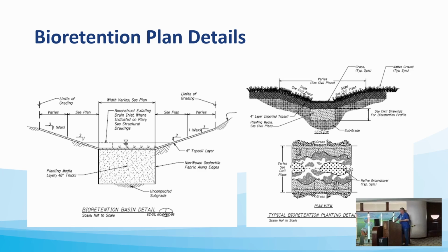The engineered soil, a blend of sand, compost, and topsoil, acts as a natural filter, reducing flooding risk and protecting water quality by removing sediments, nutrients, and other contaminants from runoff before it reaches our waterways and groundwater. The plant media mix design uses several native plant species to act as a living filter to mimic pre-development hydrology, also diversifying plant species to avoid loss of vegetation in the event of pests. Drought-tolerant plants were selected to promote sustainable landscaping and to minimize irrigation needs.